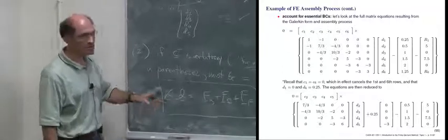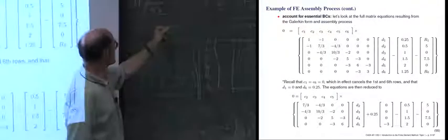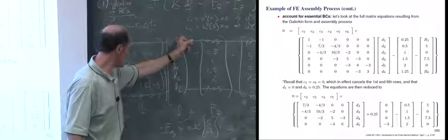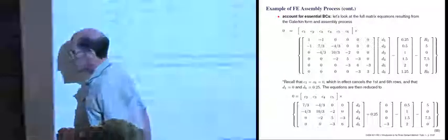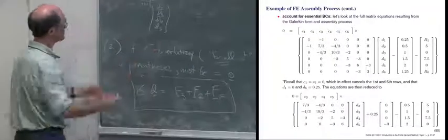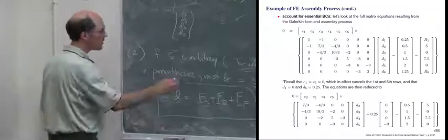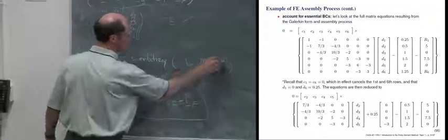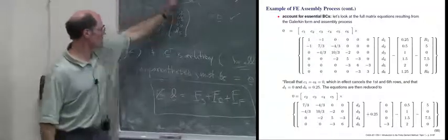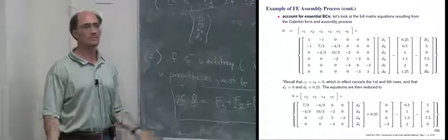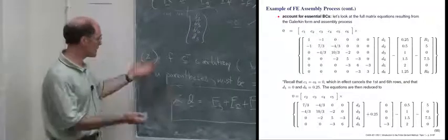So does that make sense? That's a subtle step. First of all, the first subtle step was applying the essential boundary conditions, which did things on C1 and C6 based on what was on D1 and D6. We applied that there. We then see that we have this system, but we still don't know what to do here. So we recall that from our weak form, in our Galerkin, this weighting function can be anything where the boundary conditions are not prescribed, the essentials. So that means that has to be 0. Okay? So that's it. So we can solve that system of equations.